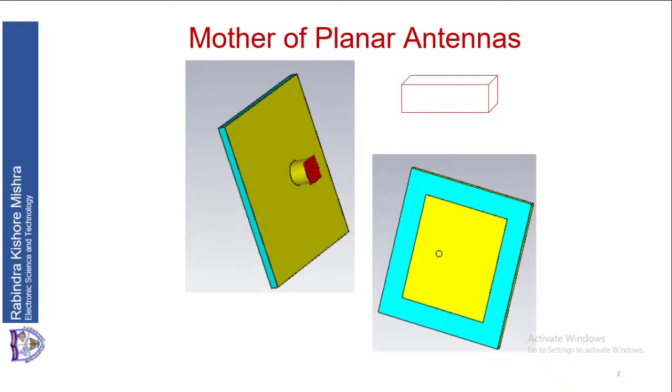Now, when we excite this antenna at its resonant frequency, a strong field will be set up inside the cavity, and a strong current on the bottom surface of the patch will be excited. This current will produce significant radiation that gives a good antenna. Now, let us try to understand why it will radiate.